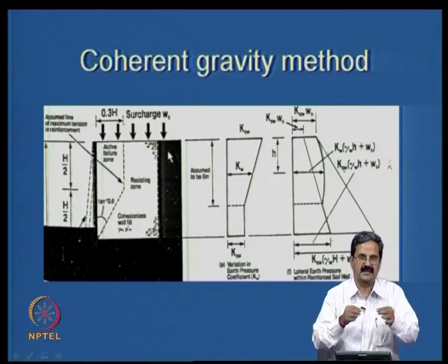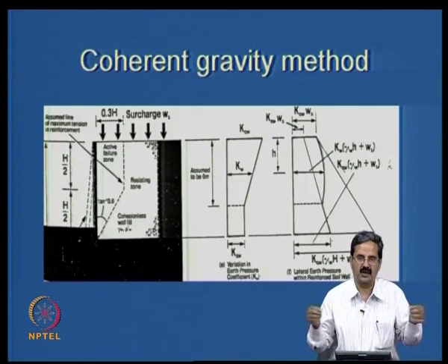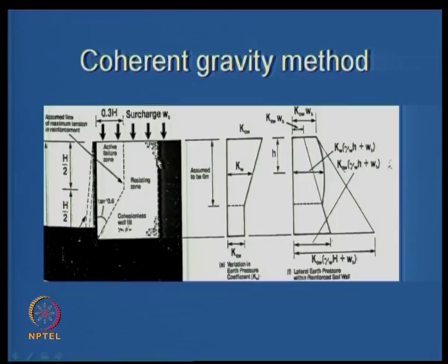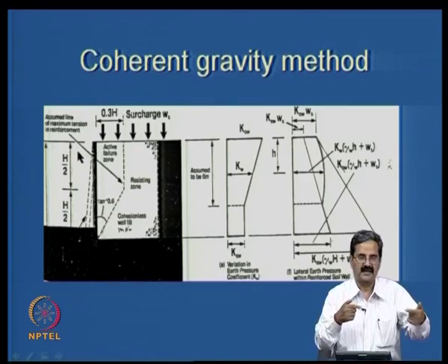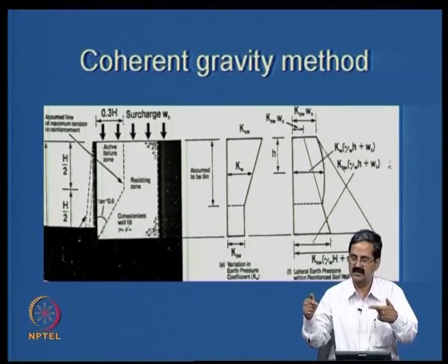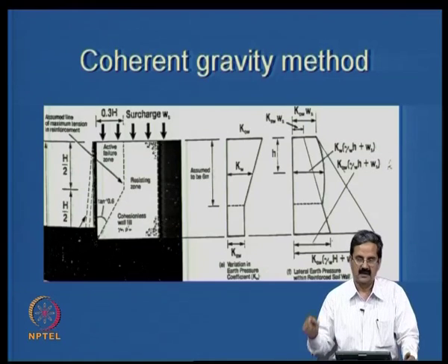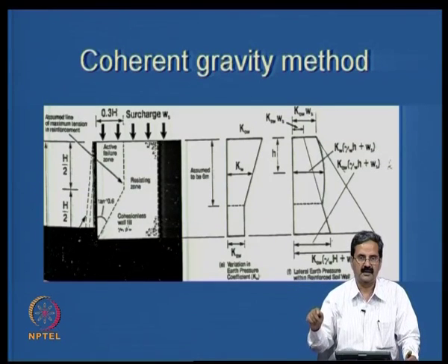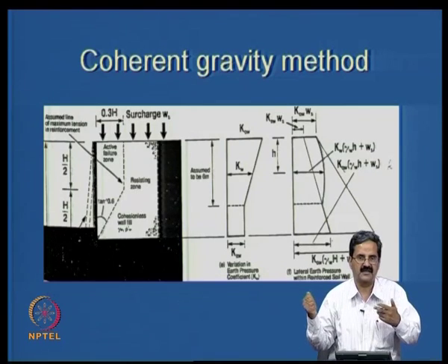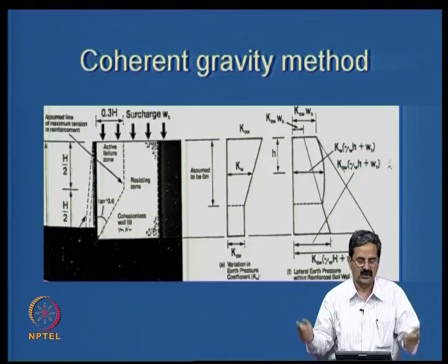You can measure the strain along the reinforcement, the entire length of the reinforcement, and in this zone what happens is that if this is the lateral force acting, the tensile strain direction will be in the opposite direction. The strain measurements will be like this, and beyond the failure point, they try to hold it. The direction of strains would be different on both sides.